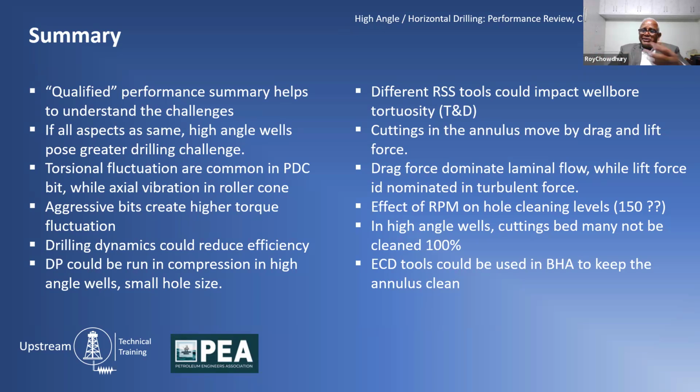And sometimes there is a term in the industry that they call push pipe. They use it above 45 degrees, because in a horizontal well, you are unable to go further. So obviously you are trying to push the pipe. So you are calling it pushing the BHA. So they call it push pipe.